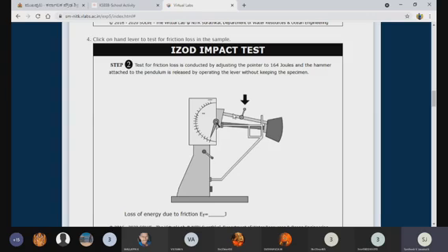Now we are placing the sample. Then you release the pendulum, at the same degree. Now this will show the 6th division or 5th division. So the 5th division means 10 joules, right? Initially it is 2 joules. Now you need to remove the 2 joules, meaning 10 minus 2. Already 1 division plus 4 divisions becomes 5 divisions. Now it is 10 joules. So 10 minus 2. X minus Y is equal to U, that is the actual energy absorbed by the material.